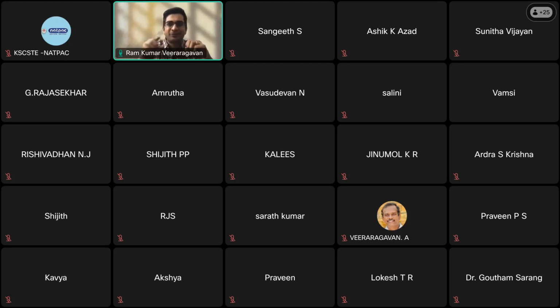Why I'm saying this is that your locally available aggregates would differ, and your binder source would change eventually, because the amount of stuff they add in the crude oil refining would change significantly. So your specification also would change eventually, and that would accommodate balanced mix design. Changes in specification would play a role for different mix types and the agency's requirements. It's up to the agency to decide what they need.